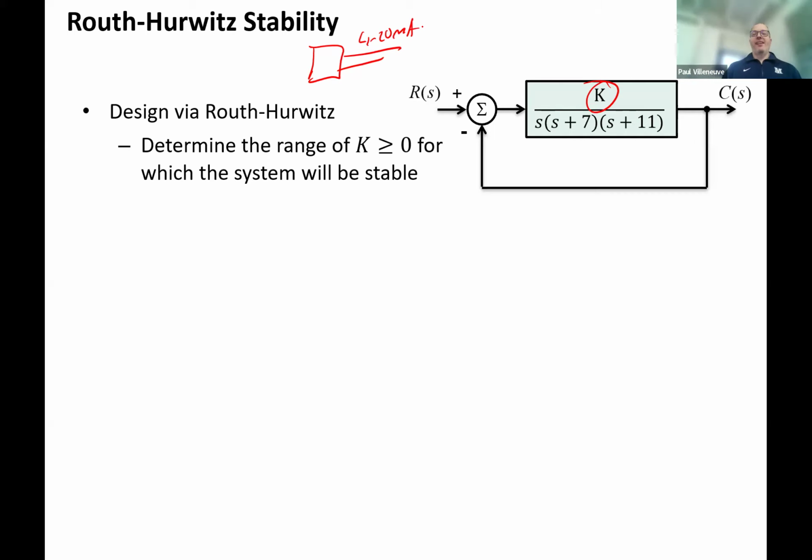You always see a signal. Yeah, exactly right. I have to have a wire that goes back and forth. What if that wire is broken and it was 0 to 20 milliamps? You wouldn't know. It would be sitting there saying, hey, I'm not commanding any output, so it's 0 milliamps. So no problem, let's run all day. So the reason why they run 4 is you at least know the wire is not broken. And there actually is a feature on these controllers called broken wire detection to say that's what's happening.